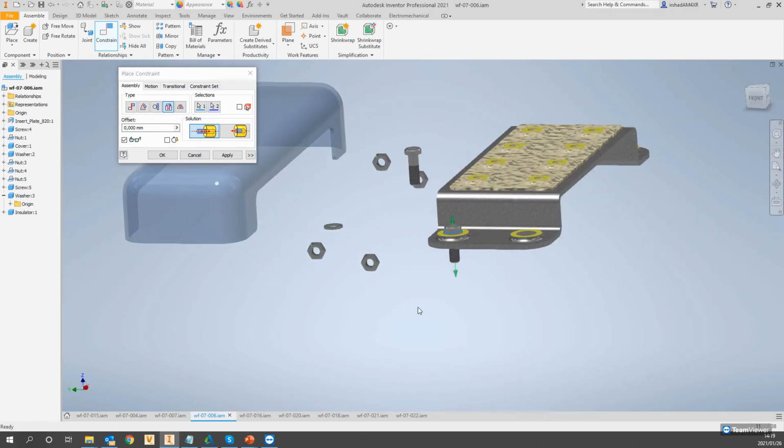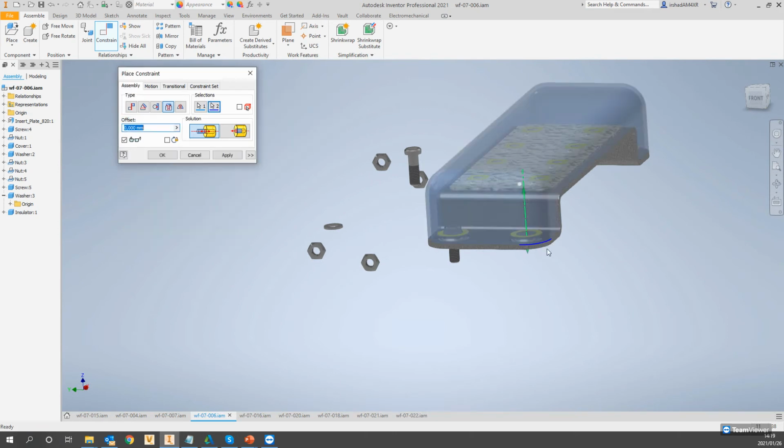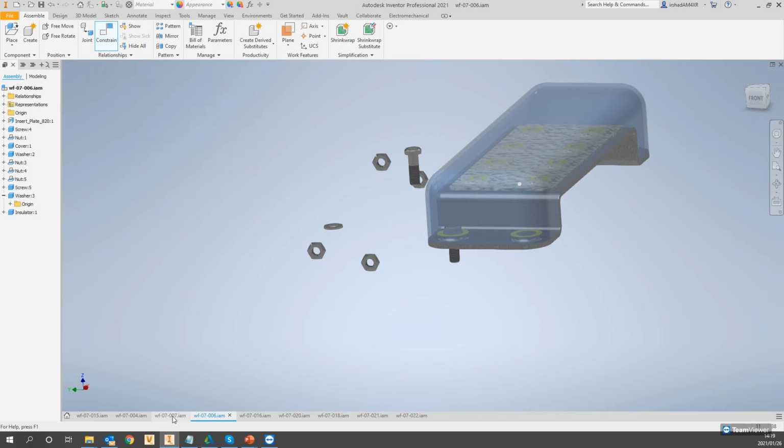And it fits it in cylindrically in one shot, right? You can also do this with, for example, the cover. You have an edge that you want to mate with the cylindrical center. You can do it here and there, for example, and you've placed your cover on in one shot. So very useful.